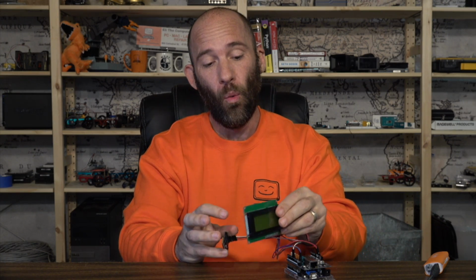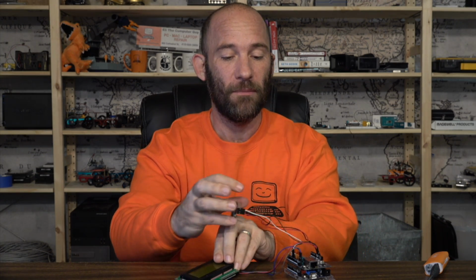Well, that's where we get into quirkiness, right? With me doing these projects and playing around with the Adafruit Ultimate GPS, using the Adafruit library, I may get a different result using a different library in the future, but currently using the Adafruit official library for the Adafruit Ultimate GPS, what I have found is when I connect this Adafruit GPS to a standard Arduino Uno, the coordinates are way off.